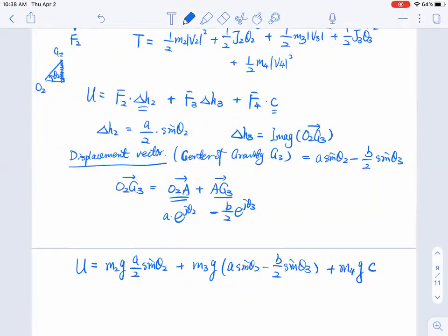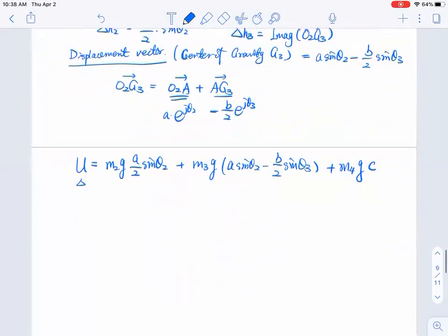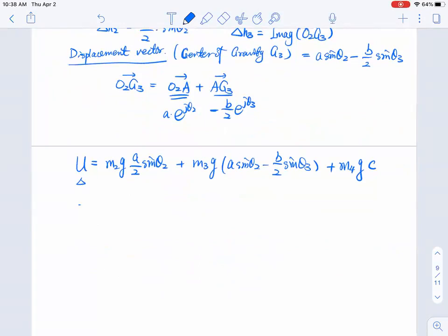And then your kinetic energy is always the same, no matter if you consider gravity or not. So you have T and U. And then in order to calculate the input torque, we know that the input torque times theta 2 dot, that's the input velocity, these two together give us the power generated by external excitation. So depending on how much power you generate, it is minus instead of positive, okay.